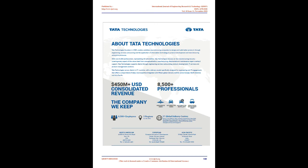Benefits and improvements of methodology. 1. Identification of air leakage paths in the early stage of the project is possible and can relate to physical test. 2. We can analyze the leakages in the CAD stage only, which can be iterated many times. 3. Potential leakage path analysis is done in CAD review and solutions can be identified such as plug, expandable tape, or baffle in the CAD data phase itself.